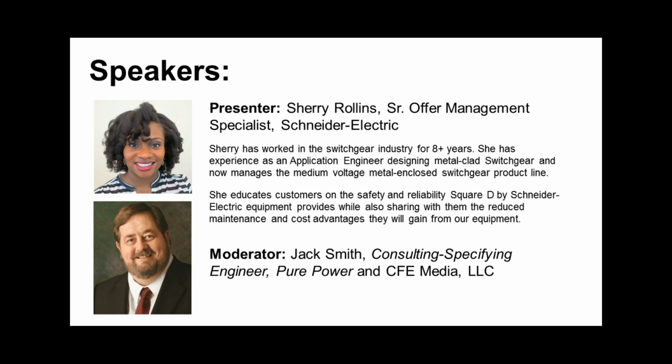And really the value proposition of SF6 from an economy and footprint point of view starts to make real sense at 27 kV and above. It just becomes so much more cost effective and so much smaller than typical 38 kV metal-clad switchgear that for 27 and 38 kV applications, one really should consider gas-insulated switchgear. Was there another portion of that question I need to answer? Yes. What advantages or disadvantages does SF6 have with fixed versus withdrawable switchgear?